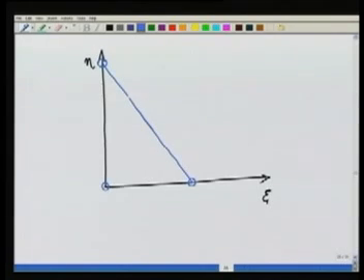If the projection of the quadratic on the first edge is a quadratic, I have the basis functions on this edge defined with respect to the corners. Then the simplest way I can define a quadratic on the edge is put a middle node here. Similarly, I look at this edge. On this edge, I know that the quadratic defined over the whole triangle, when I look at its projection on this edge, also has to be a quadratic. So why not define a middle node here?